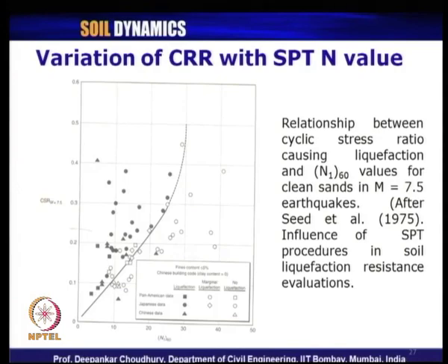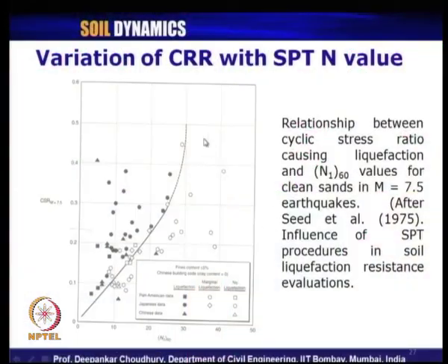That is why most parts of geotechnical earthquake engineering are very recent, very vibrant or very modern in nature, because once a major earthquake occurs, from the field investigations of phenomena like liquefaction, one can get more data points which will give the researchers community a way to identify the actual boundary between a liquefied zone and a non-liquefied zone in terms of this CRR and the measured, corrected SPT value. So, that is why even this design chart proposed by Seed et al. 1975 has now become almost obsolete.